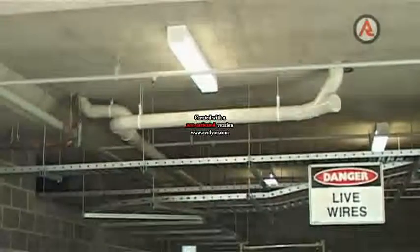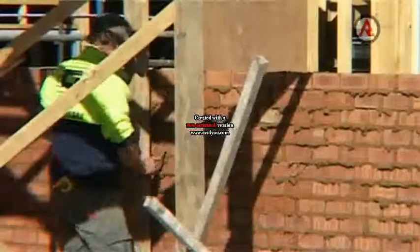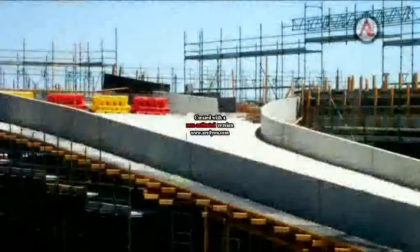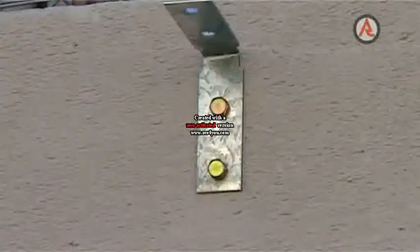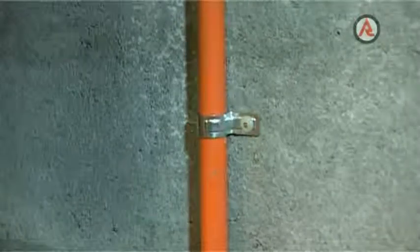in the mass. In most cases, the only problem in fastening to concrete is ensuring that the fastener can be located to avoid the reinforcing steel. Masonry materials vary considerably. Some provide strong, secure fastening, whilst others can carry only light loads due to the low strength or design of the particular material.